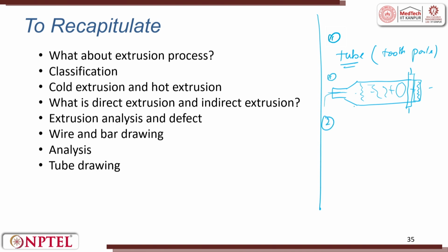Second thing is, I would like you to take a very thin sheet of aluminum or whatever it is, and try to make a hollow cylinder. Then on top of this cylinder, you try to stick or put something like Fevistick or something like that. Then through this you try to pressurize water. You will see at some point of time this weld will yield out, or there will be water leak through this. This will tell you the importance of seamless pipes.